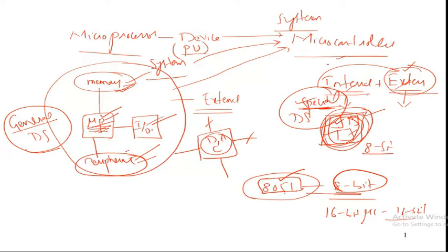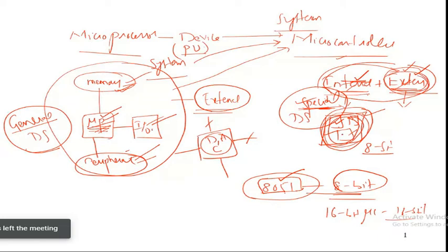The microprocessor has only external memory. There is no internal memory for the processor. But for the microcontroller, we have both internal memory and external memory. It provides an internal memory. At the same time, if that memory is not enough to run more applications, we have the possibility to extend the memory to some size, which is also restricted, by interfacing some amount of memory externally to this microcontroller. So it has both internal memory and external memory. So what is the size of internal memory it has?